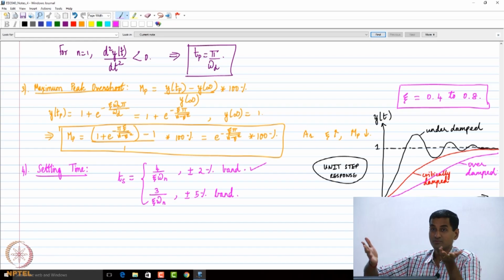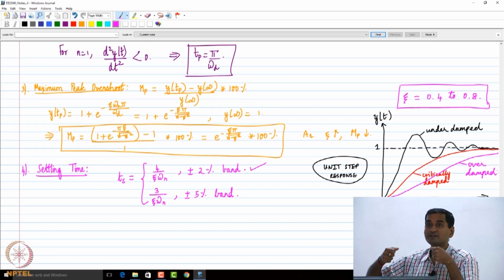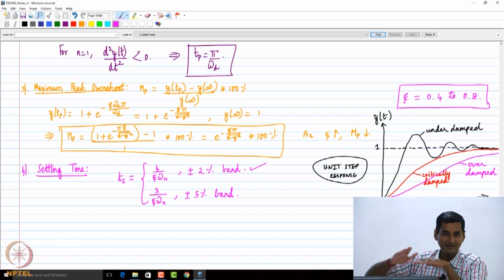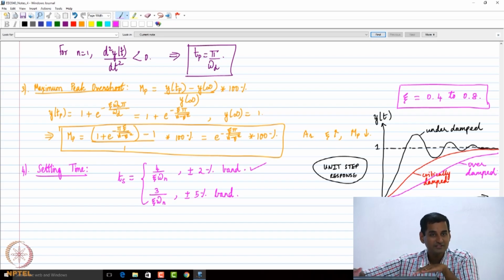You don't want to be in a vehicle traveling behind another vehicle that suddenly comes and goes forward and backwards. When it's stopping, you want a smooth, nice motion. But you also want the system to act as fast as possible. So you have two conflicting requirements. Then what you do is design it as a critically damped second order system.